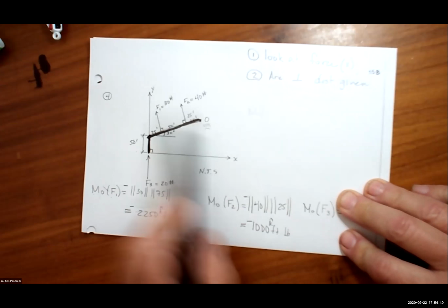Okay, and now I'm going back to the module. So you have the videos, watch them, go over all the problems, and then do the homework. Okay? And on Thursday, we're solving it vectorially, meaning R cross F. We're going to find the R vector in vector form, find the F vector in vector form, and the moment is going to be R cross F. You're going to like this initially because it's easy.